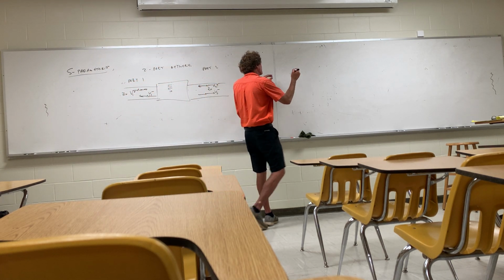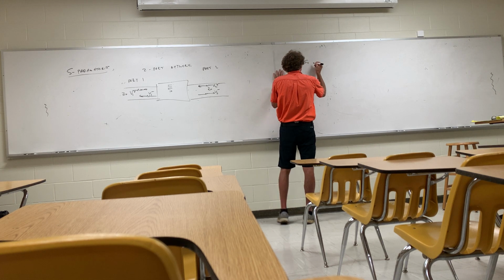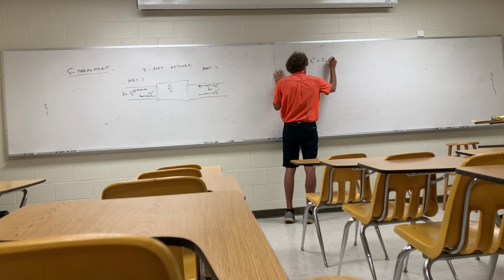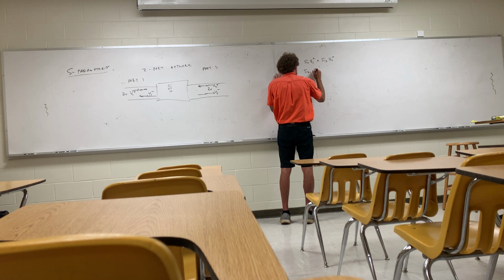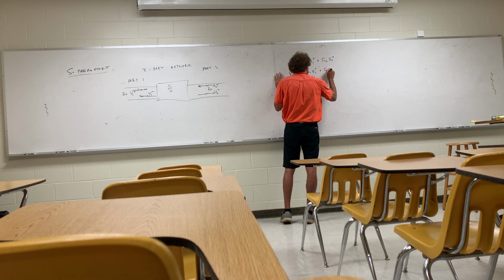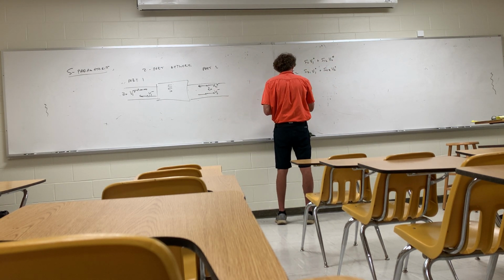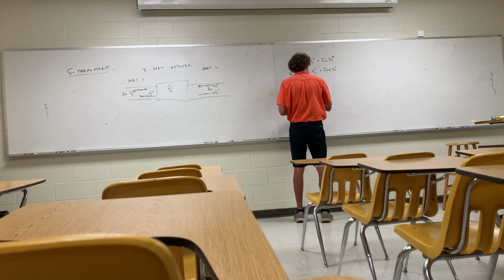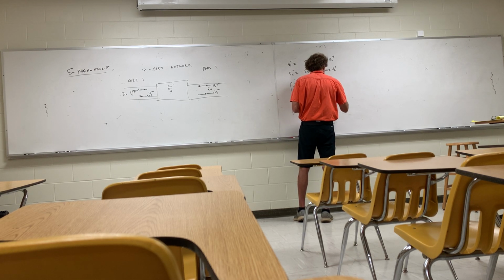And the relationship is through the S parameters. V1 minus is equal to S11 times V1 plus S12 times V2 plus, and V2 minus is equal to S21 times V1 plus S22 times V2 plus. The way it's usually written is like this. V1 minus, V2 minus in a column vector is equal to the matrix S11, S12, S21, and S22 times V1 plus, V2 plus.